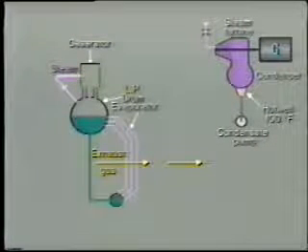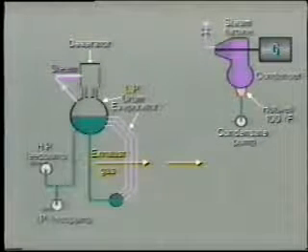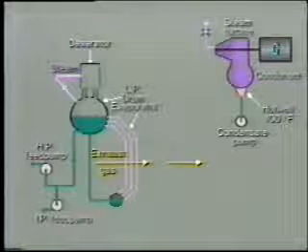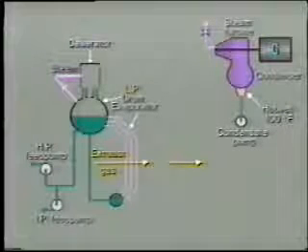The steam drum acts as the de-aerator storage tank. De-aerated water from this drum or storage tank supplies the HP and IP feed water pumps, as well as the LP evaporator. So in this arrangement, all of the feed water, which is demanded by the HP, IP, and LP sections, must be fed into the de-aerator as condensate. The condensate pump is designed with sufficient pressure and capacity to feed enough water into the de-aerator.